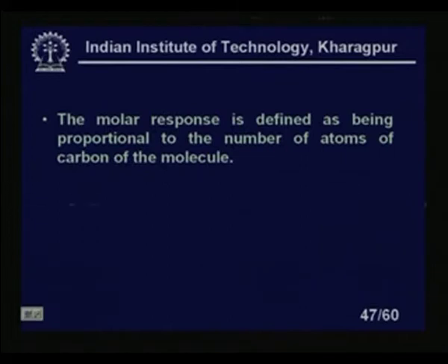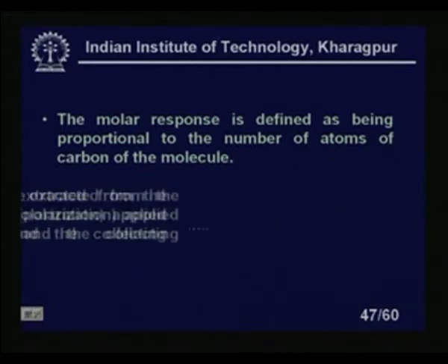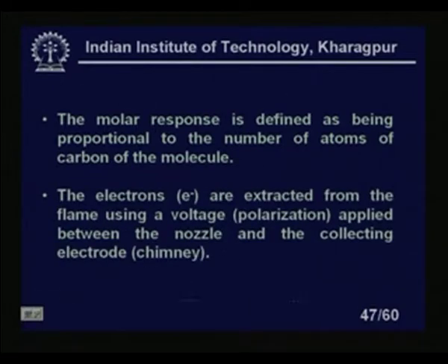The molar response is defined as being proportional to the number of carbon atoms of the molecule. The electrons are extracted from the flame using a voltage polarization applied between the nozzle and the collecting electrode. Okay, between the nozzle and the collecting electrode.